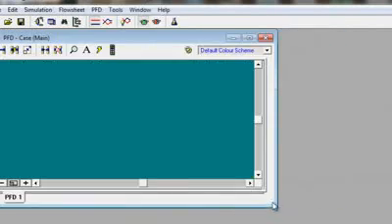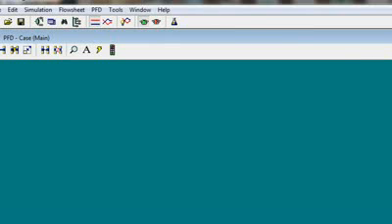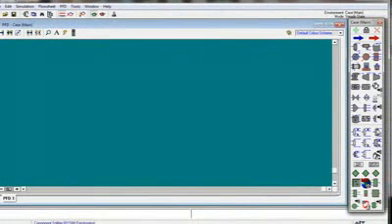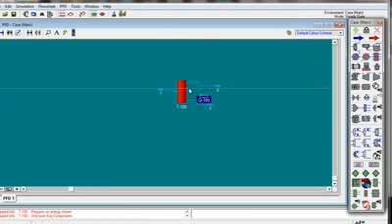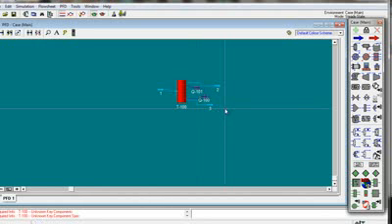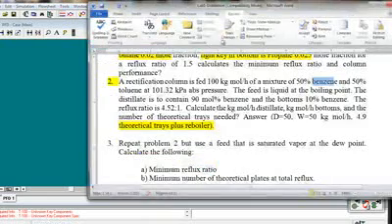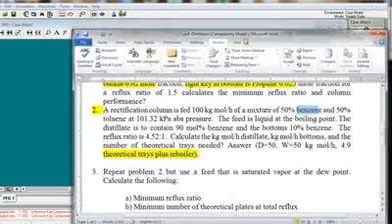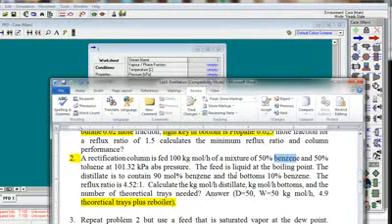We enter the simulation column. It's fine. We choose shortcut column, which is here. We drag the streams out and in. Also for the heat streams, we can drag them out. And now we add. We go to see the specification. Here we have the temperature, or we have the pressure.